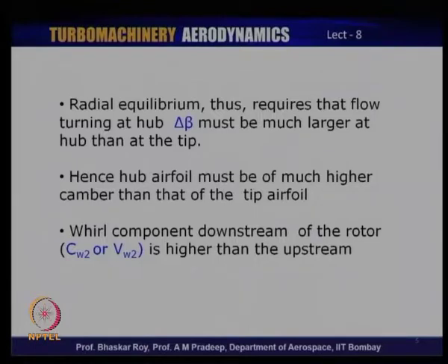So, as you can see, the camber would indeed vary from hub to tip, which means you would essentially have different aerofoils at the hub and at various sections all the way up to the tip. They are indeed different aerofoils, not the same aerofoils. And then thirdly, the whirl component downstream of the rotor would be higher than the upstream. The change of whirl component is of course the work done. So, since work is being put in, it stands to reason that the downstream CW, or whirl component, will be higher than the upstream one.